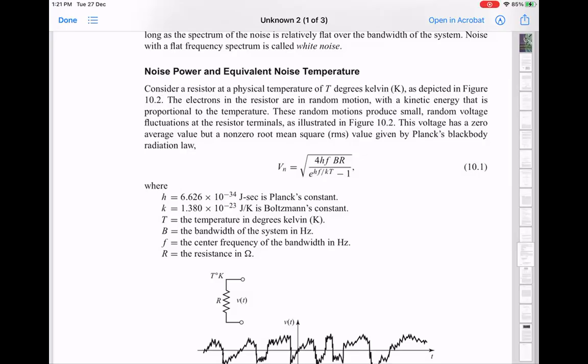But the point is that an amplifier just doesn't take what is at the input and create a larger copy, but it has to add some extra noise. Quantum mechanics tells you that this noise needs to have a certain minimum value. But most commercial amplifiers available today do much worse than that. This noise is much higher than it needs to be as specified by quantum mechanics.